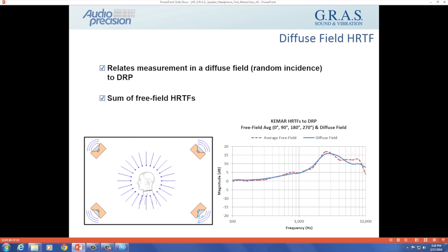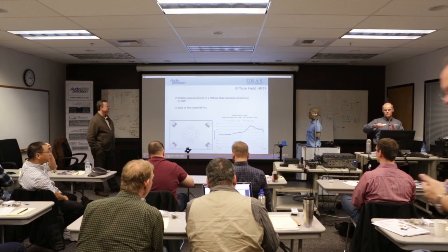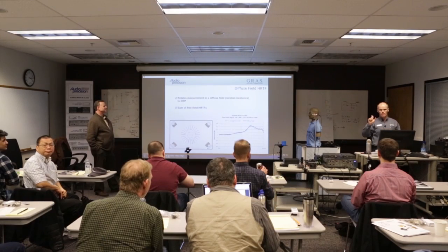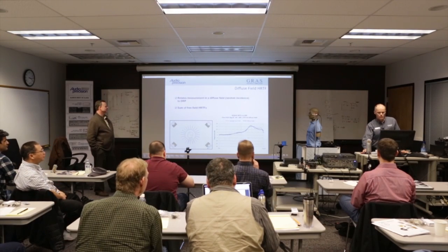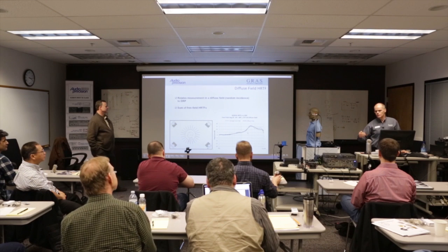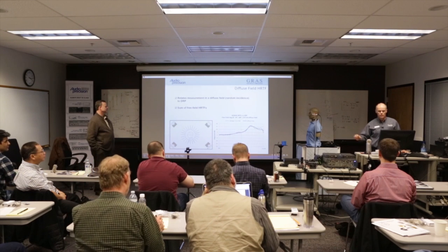When you look at the calibration sheet, you'll see a great big resonance up around 10 kilohertz. That's very high Q. And it's really this head-related transfer function that you should use to relate the measurement inside the ear to the free field.